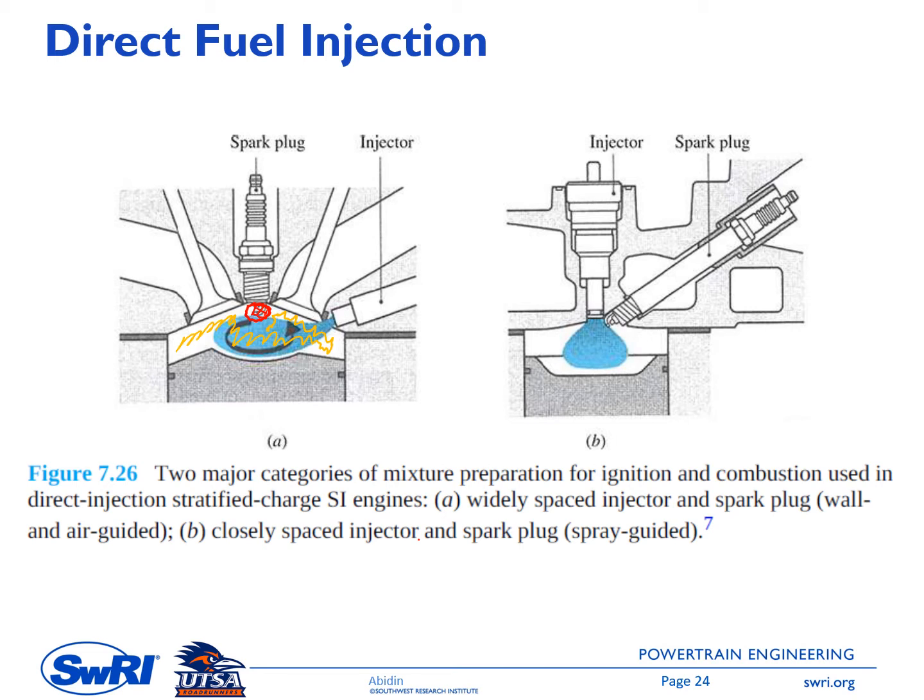And then for type B here, the fuel mixture composition will be guided by the characteristic of the spray. So you can see on the schematic that we have a kind of unique injector that can produce a wide spray angle. Here I put a purple.